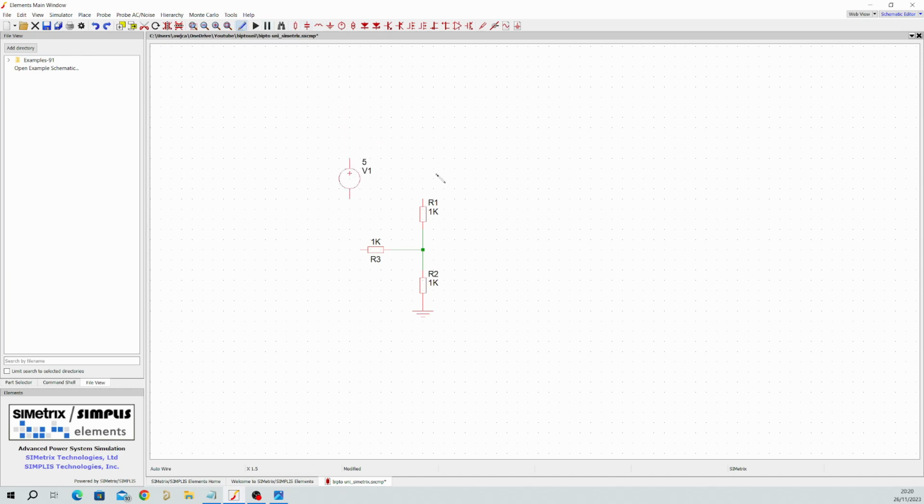Now the voltage reference obviously feeds this network, but it would also power the rail-to-rail input output amplifier, and it would also power either the ref high input to your microcontroller, or in the case of a discrete ADC, would power the discrete ADC, because these ADCs don't take much current. So I'm just going to change the values of these, and I'll tell you why a bit later.